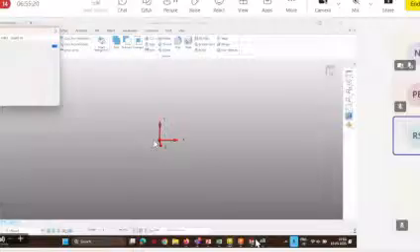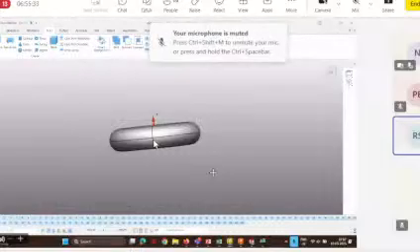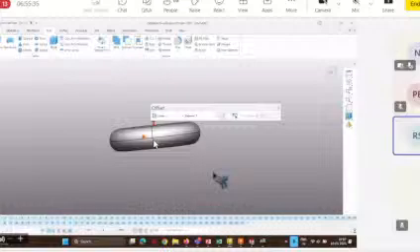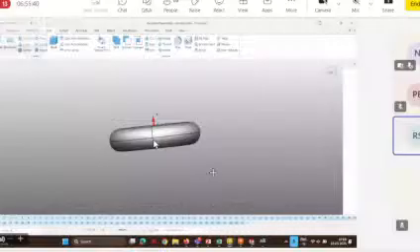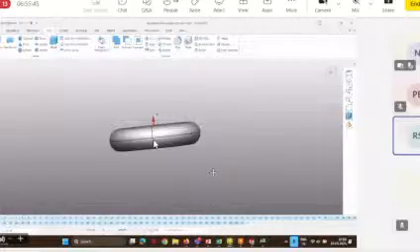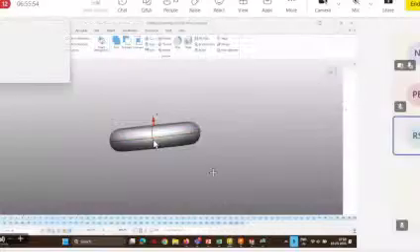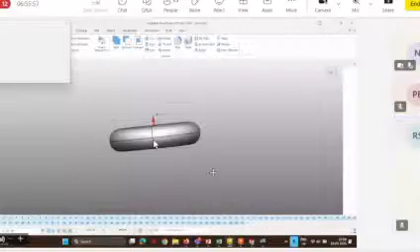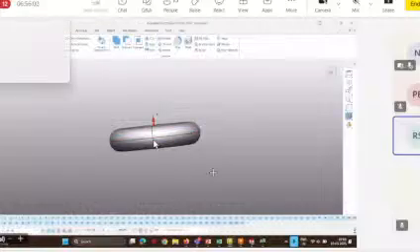And since you're depositing the inner area fill with the fixed strategy, the calculation is not taking that much time because most of the time is taken depositing the outer contour only. And there also this contour is giving multi-axis, we are using it. So there is no issue of any material dripping or anything like that. And whatever overhang will come, even 90-degree overhang is possible to deposit with this strategy.